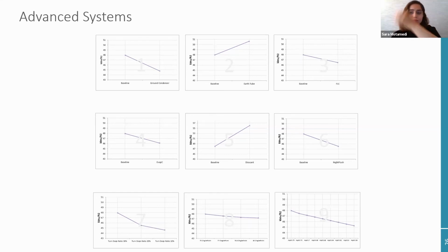I found it very fascinating that maybe the architectural envelope impacts are not very effective here in San Francisco, and we need to focus more on some of the MEP systems, whereas in Chicago you can really have a big impact through the architecture.